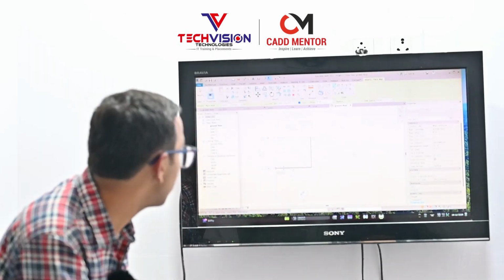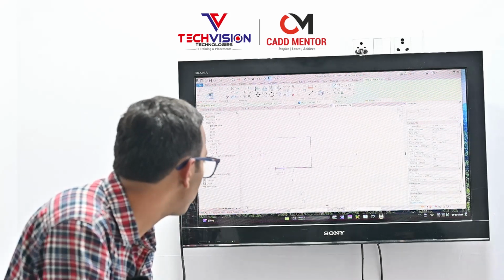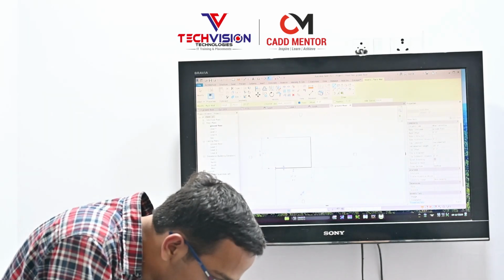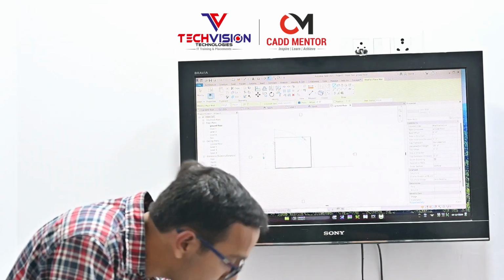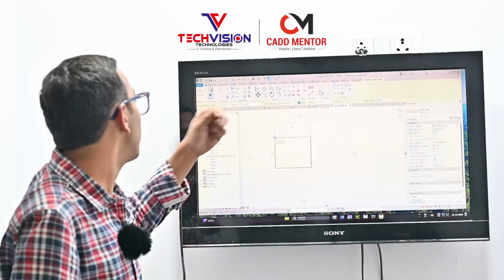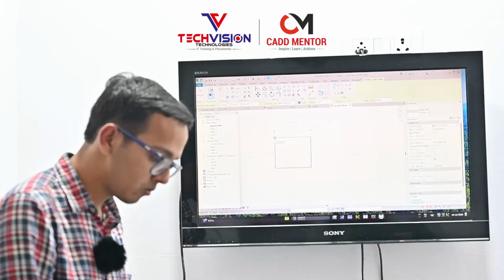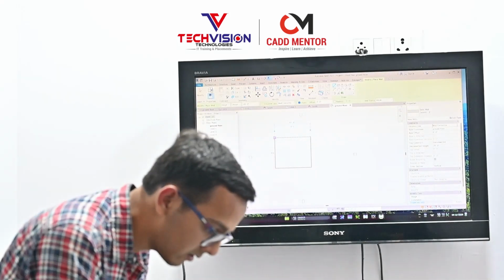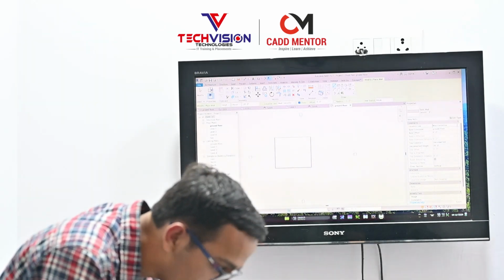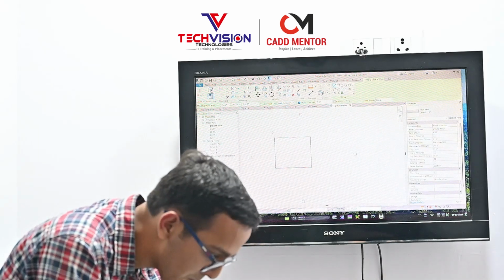And then you can see, after first we took the 57 feet 6 inches, then it has taken the 57 feet 6 inches to the exterior of the wall. So here you can see the location line where you can select the wall center line. If you want to give the wall, the basic 6 inches wall, in the center line of the project, you can change it from the location line. So here we are taking this wall center line to the core center line.